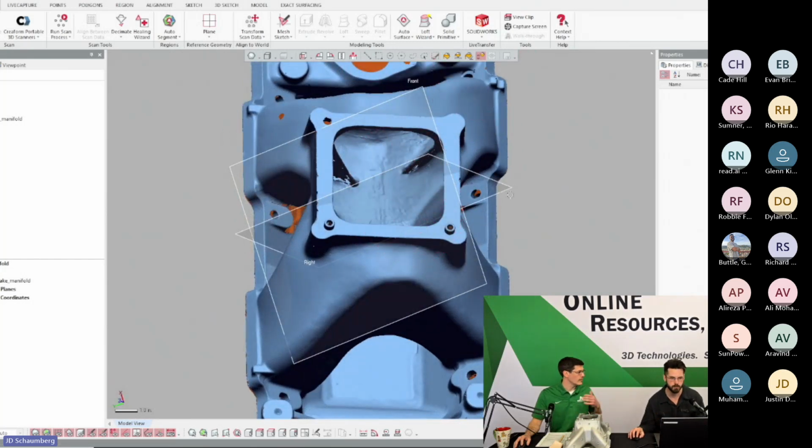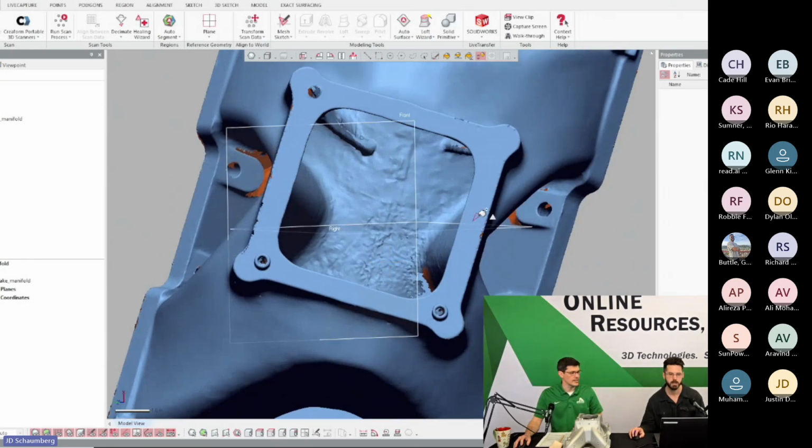So when you go to front face, right, you can do that, and when you finish, the model will then be on the origin. Oh, okay. So that the model is in the correct model space. Cool. So when you bring it into SolidWorks or something, you don't have to redo this. Right. Or when you have your machined model and the person who's writing the program for the CNC machine has a true zero point they can go from that makes sense relative to the machined features. Cool. So let's go ahead and create a plane.